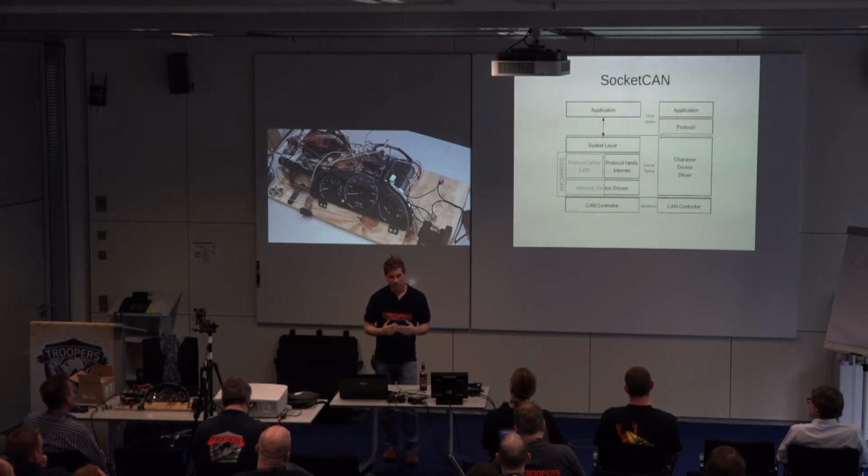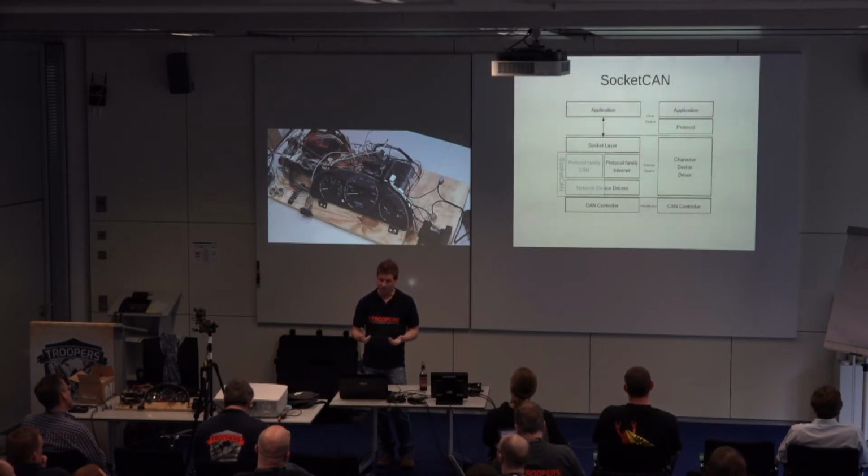Just like you'd have a normal networking socket, you can now talk to CAN the same way. Well, reasonably close to the same way. So with your typical tools, you can write things in C that would just use the socket command. Wireshark would work on the car, those kinds of things. It really makes it a very easy way to manipulate stuff for CAN.